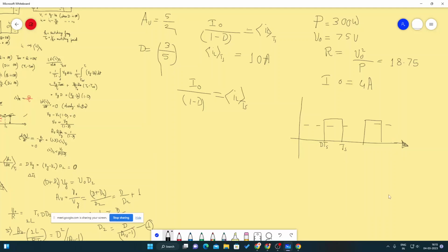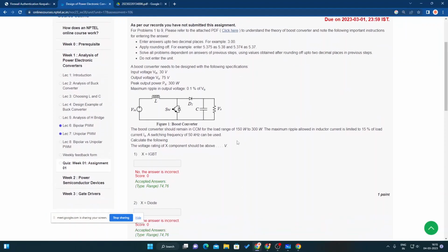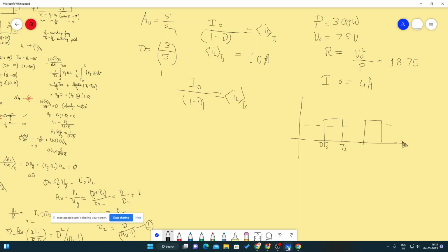Sir, actually, for the output voltage, there is given some ripple, 0.1%. If that is the case, then the switches also need to be rated for that ripple, and the peak also, I plus delta IL by 2. Yeah, we can find out the ripple separately. But for the analysis of steady state, we will assume that the ripple is very small and hence can be neglected.